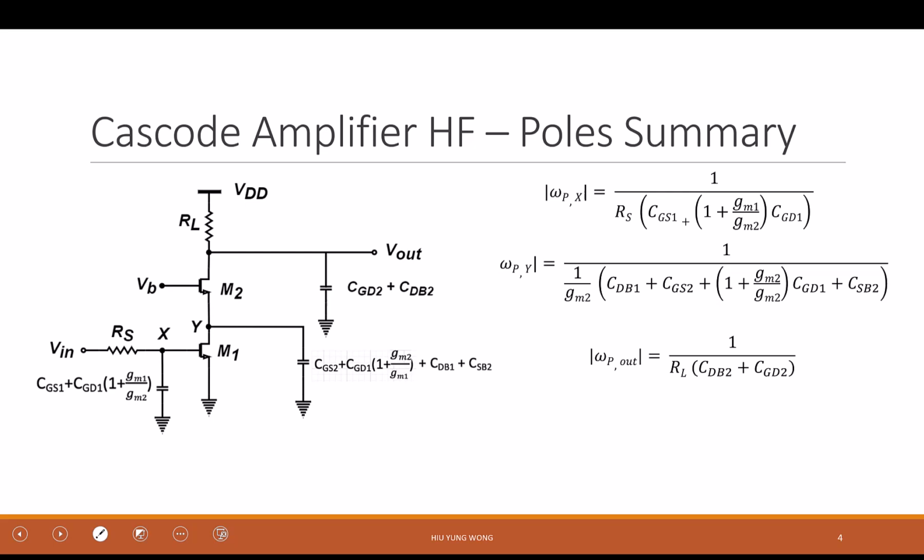And in order to find the poles, again, we start with zero bias, with low frequency, and then go to medium frequency, eventually go to high frequency. At high frequency, we care about these parasitic capacitors, right? Last time we said we have 2 transistors, so how many capacitors do we have? 8, right?